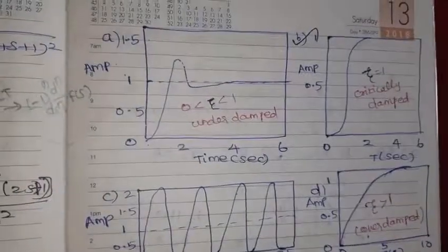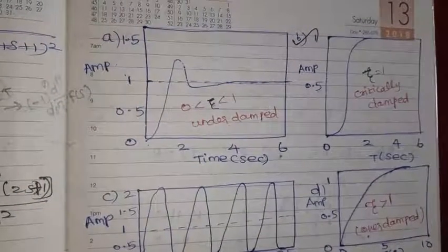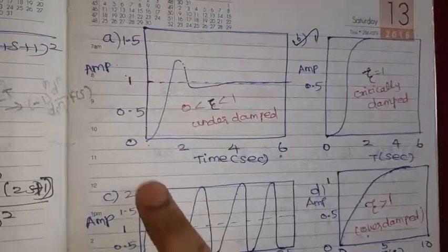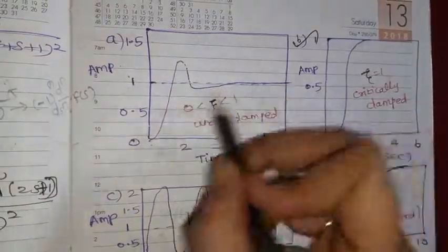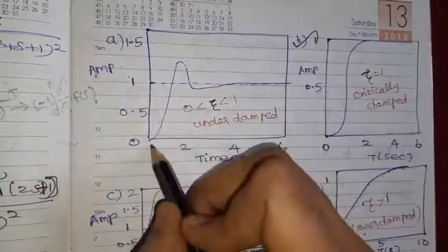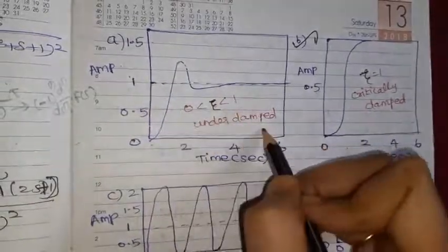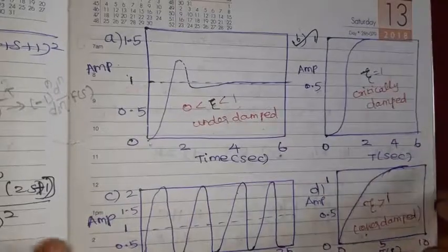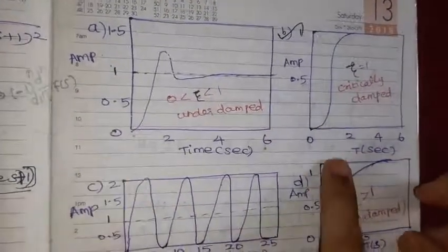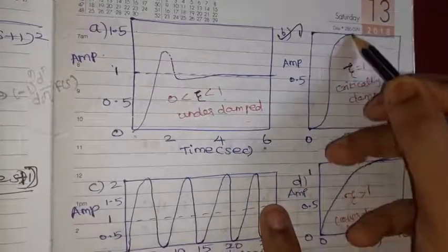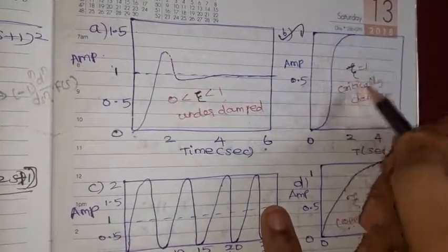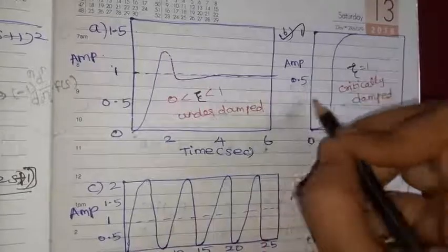So from the figure, find out for which it is critically damped. Zeta value is 1. So first option C, it is going up and then reducing. So zeta value between 0 to 1. Okay. It is an under damped system. So it is not, this is wrong. Then zeta value for this is from 0 to 1. So this is not critically damped either. So this is the right option.